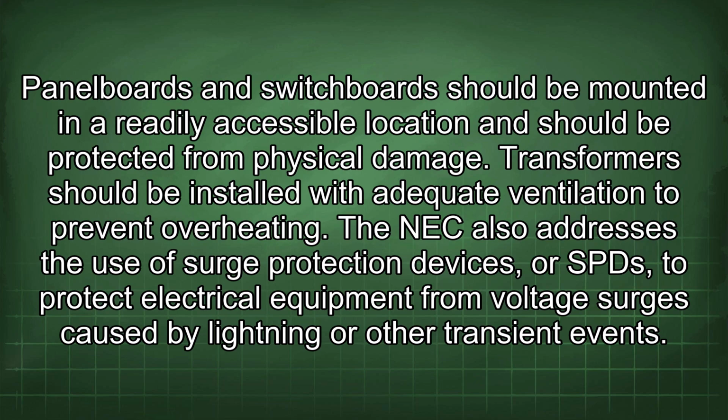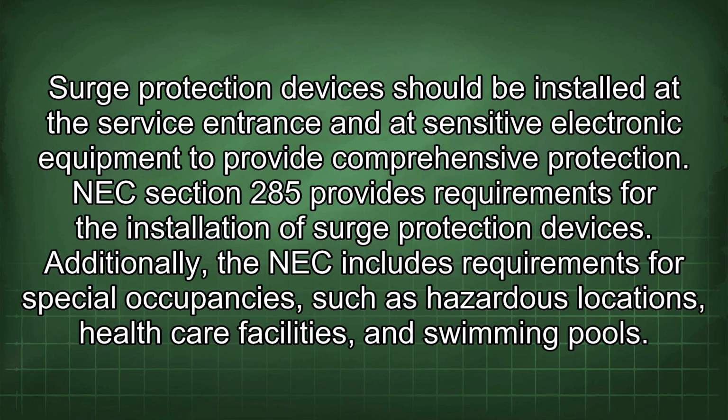The NEC also addresses the use of surge protection devices, or SPDs, to protect electrical equipment from voltage surges caused by lightning or other transient events. Surge protection devices should be installed at the service entrance and at sensitive electronic equipment to provide comprehensive protection. NEC Section 285 provides requirements for the installation of surge protection devices.